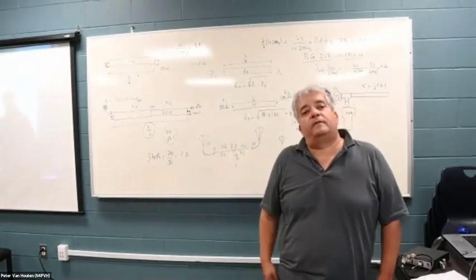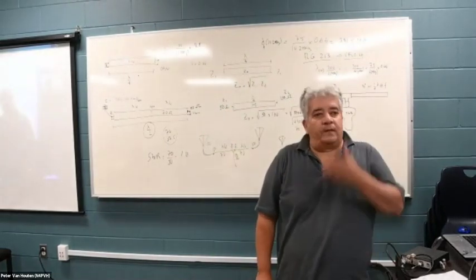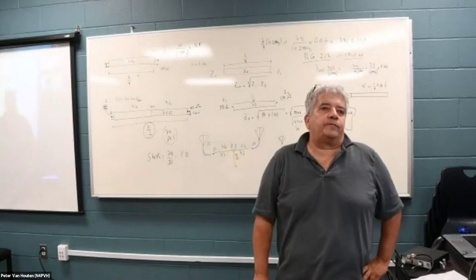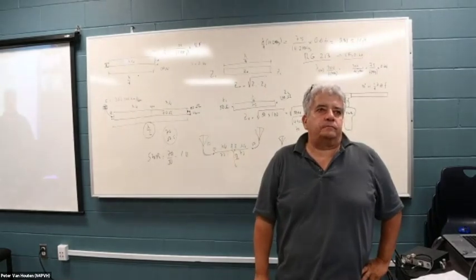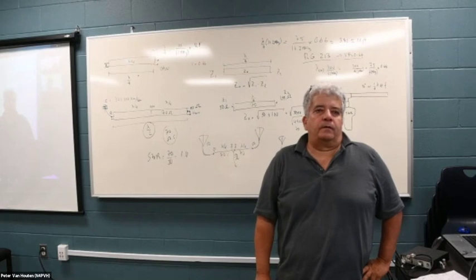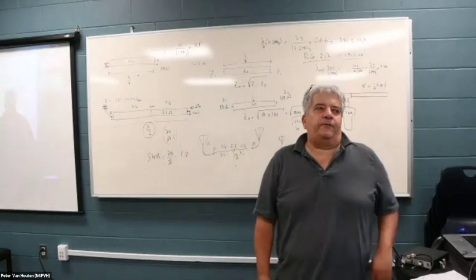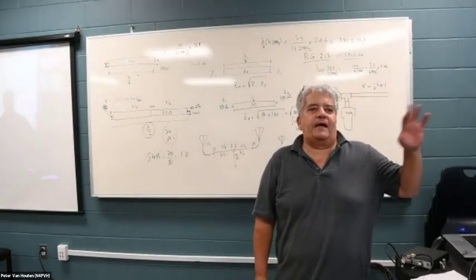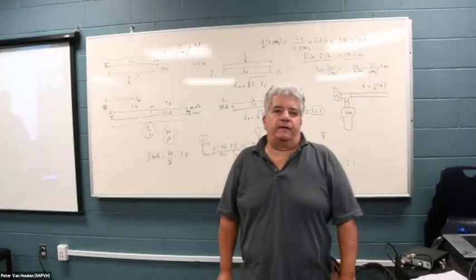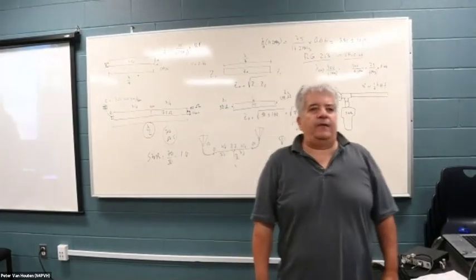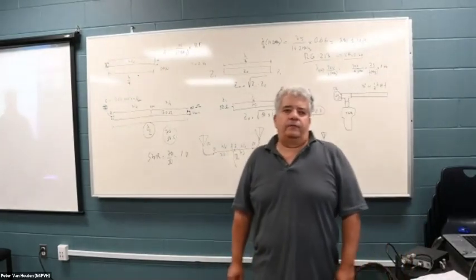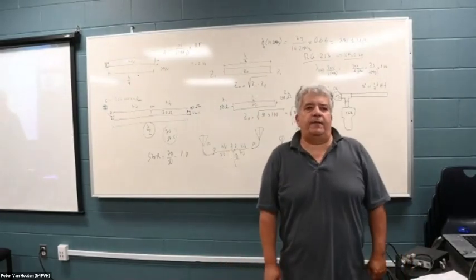Question. If I'm putting out a monobander out there, do I want a half wavelength or a full wavelength for that frequency to feed it? No, it shouldn't matter. Once you are matched, there are some myths about the magic length of the transmission line. But if your antenna is matched to 50 ohms, it shouldn't make a difference.